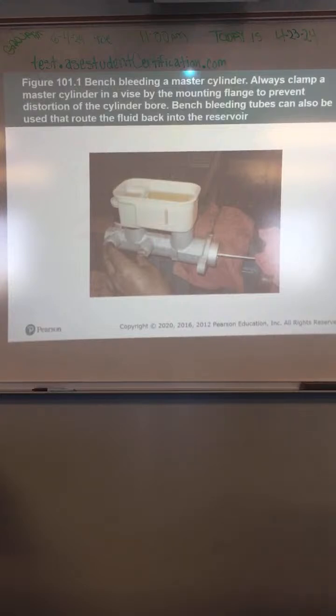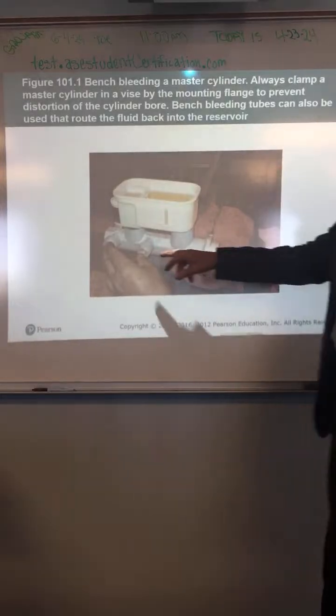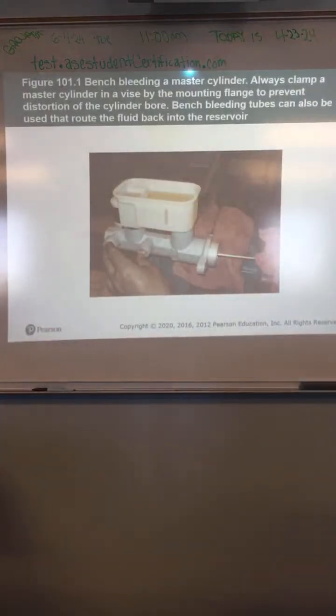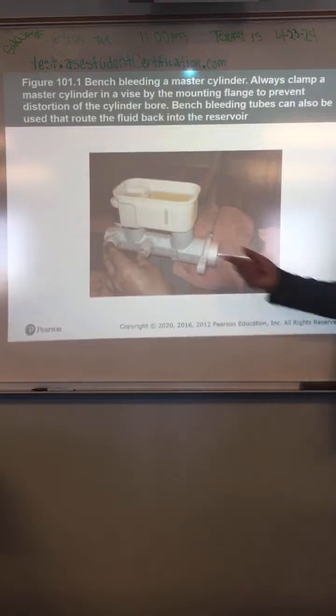Normally, if you buy a master cylinder, it comes with those little tubes and fittings that will screw into here, and then you just run the tubes right back into there. And you just take a tool and just kind of push it back and forth, right? Work it, just like you're pushing on the brake, same thing.